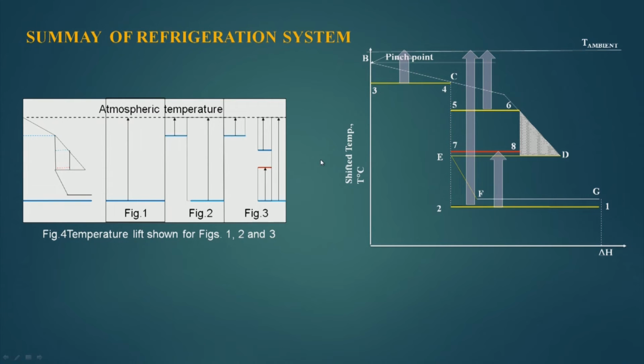So, the complexity is increasing, the number of equipment is increasing, but we are able to save the electricity which will be used in the compression. Number of compressors are also increasing, because in many cases we cannot work on high compression ratios. If the compression ratio is high, we have to break into 2 compression ratios and 2 compressors have to be used, because adiabatic compression takes more energy than isothermal compression.